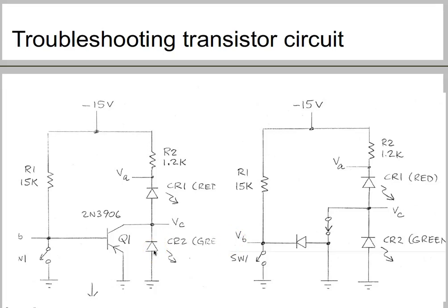The simplest way to check a switching bipolar transistor is to build a test circuit, like the ones shown in the previous circuits which you saw. In those circuits, the LED can be used to indicate whether the transistor is turning on and off like it should. If the LED does not turn on and off when the switch is opened and closed, that is, if the LED remains always off or always on, then the transistor is bad.